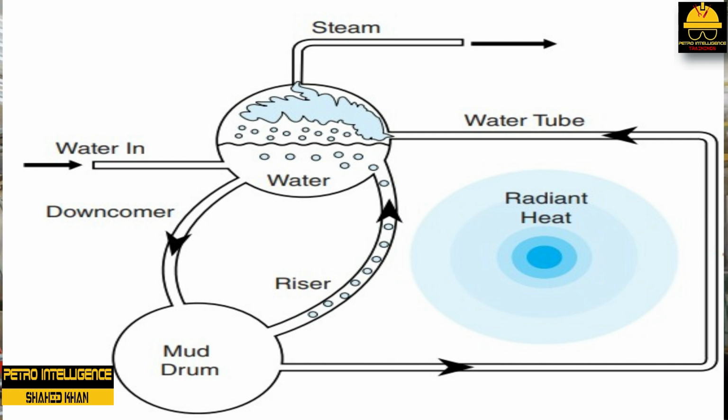Hot gases flow out of the firebox, into the economizer section, and out the stack. Water temperature increases at programmed rates. Pressure begins to increase. Steam may initially be vented to the atmosphere. As the temperature of the water inside the generating and riser tubes increases, the density of the water decreases and initial circulation is established.